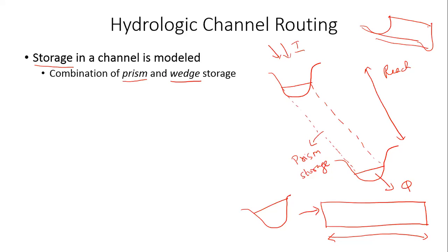Okay, so an incoming flood comes into this reach. What happens to the water level at the first cross section? What happens to the water level over here? When the flood comes in here, the water level here will naturally go up, right? It will go up something like this. Correct? Here the water level is still the same original level. Instantaneously, if you look at this entire reach, the water level here would have gone up because of this incoming flood, while here the water level still remains at the same level.